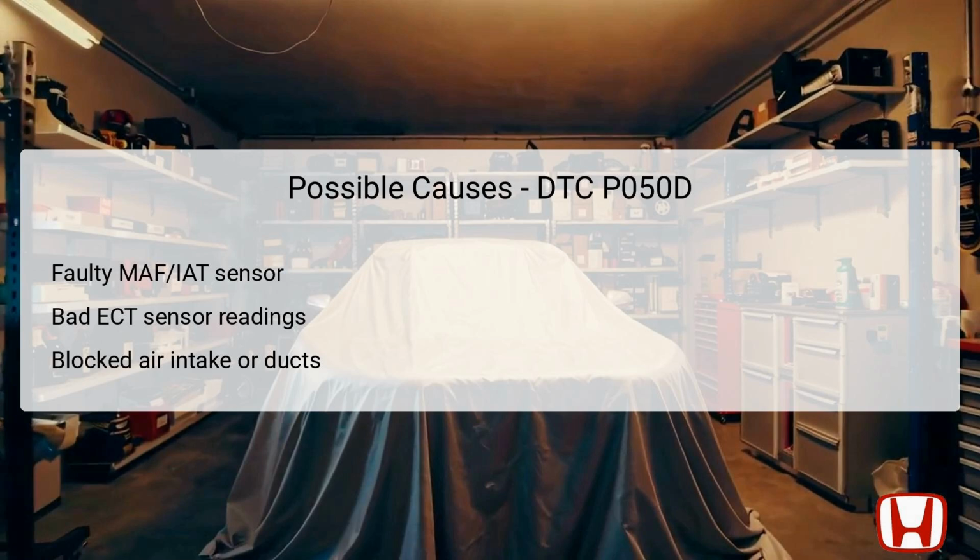Physical blockages or vulnerabilities in the intake air ducts can hinder airflow, impacting the engine's performance during a cold start. Lastly, a defective throttle body can interrupt the airflow path, necessitating inspection for dirt, carbon deposits, or physical damage. Diagnosing these components promptly is essential to rectify the cold start idle problems effectively.